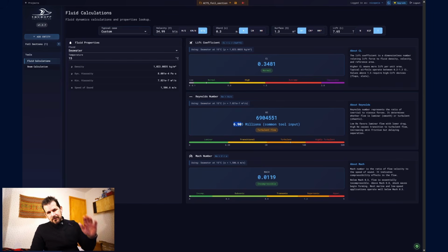And then the Mach number, I'm not going to get into it here, because in seawater, at least in our foils for the America's Cup, we're very far from having any Mach number that will impact our calculations. So in the America's Cup, more or less, we go between, while sailing and not taking off, and we'll look at the takeoff later, almost 50 knots, which will be a CL of 1.7, and the lowest value will be 20 knots, which will be 1.06.